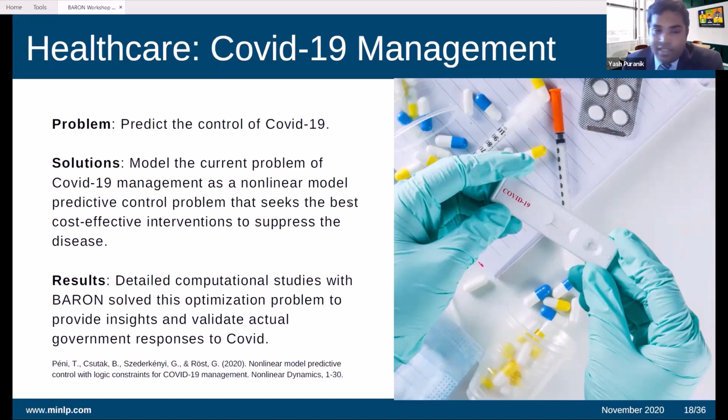So for those of you who are familiar with control theory, of course, you need measurements to decide what your control action should be. And these measurements are not always available, or it might not even be possible to measure, at which point you often use things called observers or state estimators, where you try to estimate the measurement that you need, which you don't have, with whatever else you have.